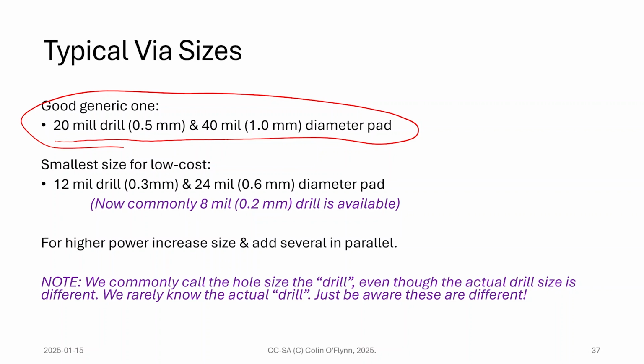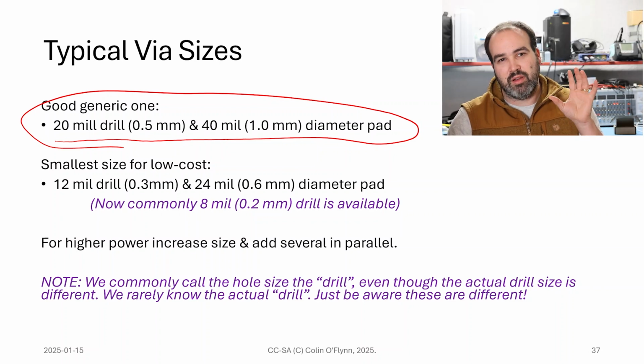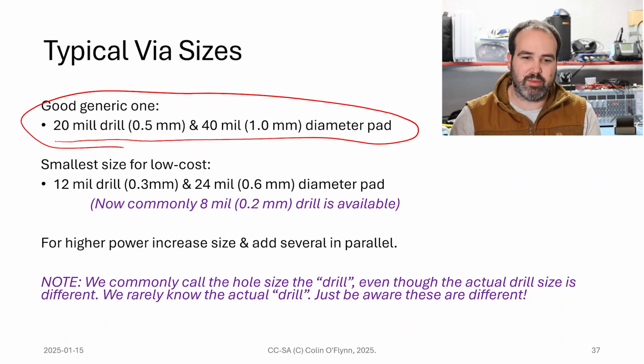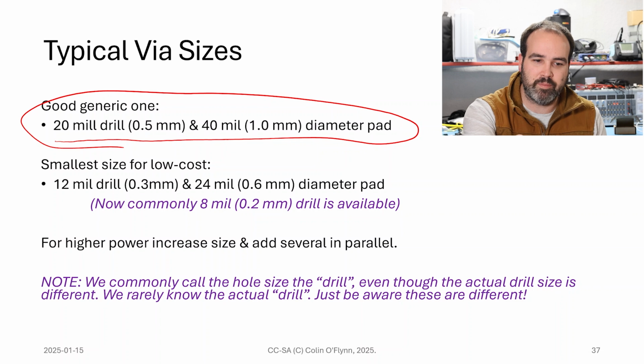However, again, caveat: if you said, I want to make this on my CNC mill, you should go look up what a good recommended drill size would be for that, because you probably want as big a drill size as you possibly can to reduce your bit breakage.